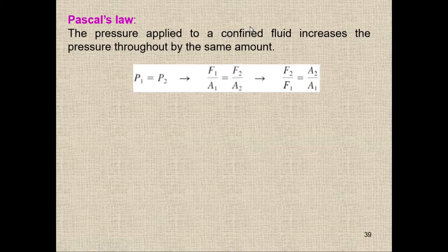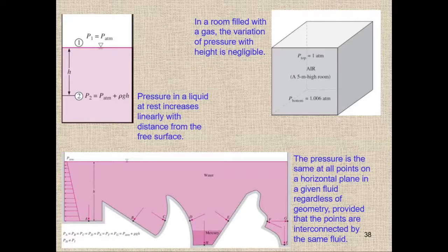And remember that the pressure is same, not the force. And the pressure is always normal. Remember, it is a normal force per unit area. In the previous example, at point A, point B, point C, you can see we have the pressure in normal directions. So again, it is always at an angle of 90 degrees.